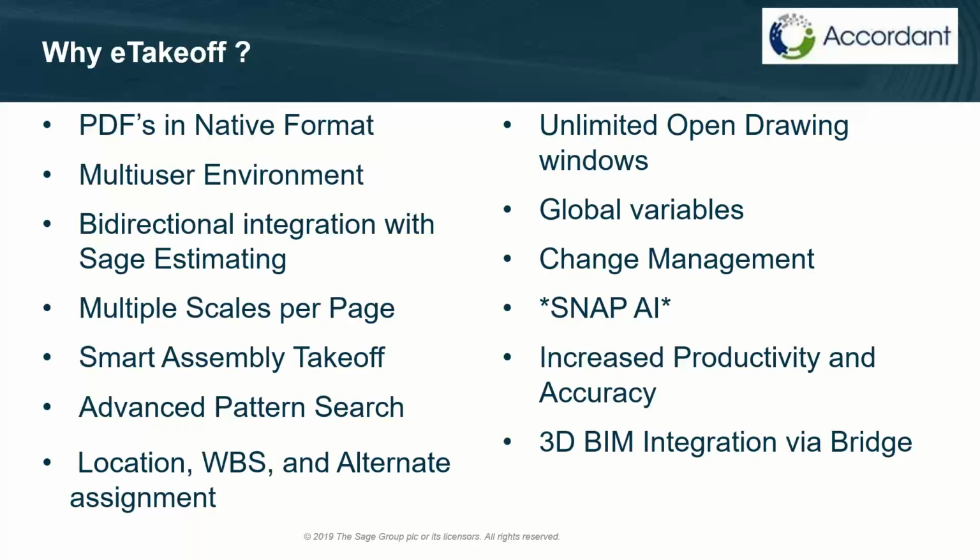Another benefit here is what we call global variables. So you have the ability for a given project to change variables globally. A good instance here is, let's say that we had done some concrete takeoff that was the 3000 PSI, and all of a sudden there's a spec change and they want all that changed to 3500.